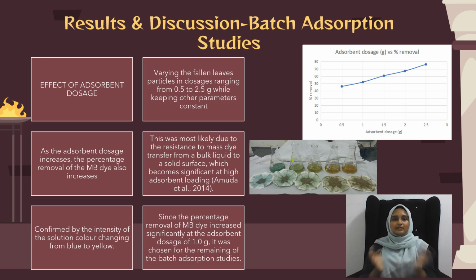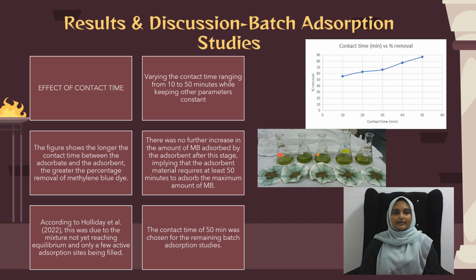Since the percentage removal of the methylene blue increases significantly at the adsorbent dosage of 1.0 gram, it was chosen for the remaining batch adsorption studies. Effect of contact time. It was done by running the contact time ranging from 10 to 15 minutes while keeping other parameters constant. So from this figure, it shows that the longer the contact time between the adsorbent and the adsorbate, the greater the percentage removal of methylene blue dye.